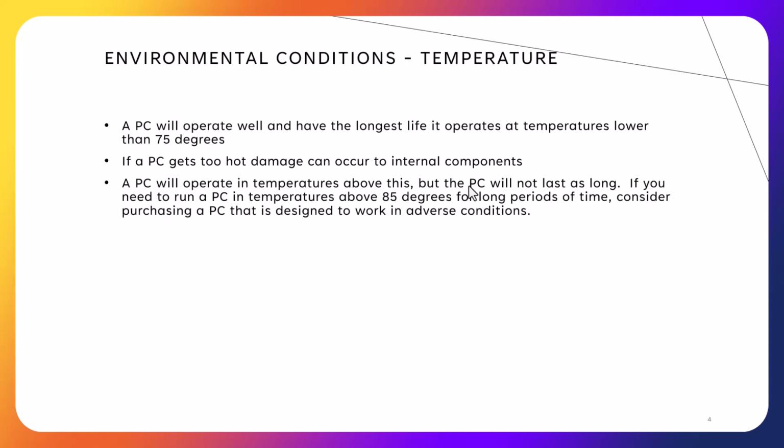A PC will operate and have its longest life at temperatures at 75 degrees or less. If the PC gets too hot, the heat can damage internal components and they just won't run right. A PC can operate above 75, but it just won't last as long. I've seen PCs run at 80 and 85 degrees for a year or two without a problem. At 3 to 4 years, you start getting weird problems you just can't quite identify. If you do need to run a PC or a laptop above 85 degrees for a long period of time, you can purchase a PC designed to work in adverse conditions.